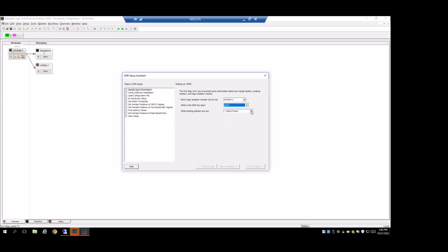In this example, we're using DDR5. We are using the FS2601 UDIMM interposer from Future Plus Systems. On the DDR5 DIMM, there are 2 channels. There's subchannel A and subchannel B. With this particular system, we only have a single module, so we're going to load just channel A, and in fact, with only one module, we're only going to see the command address and 1 byte line of data.